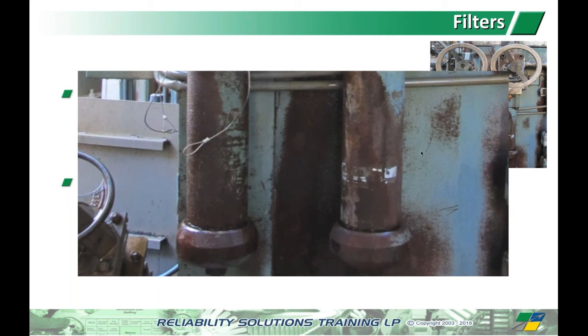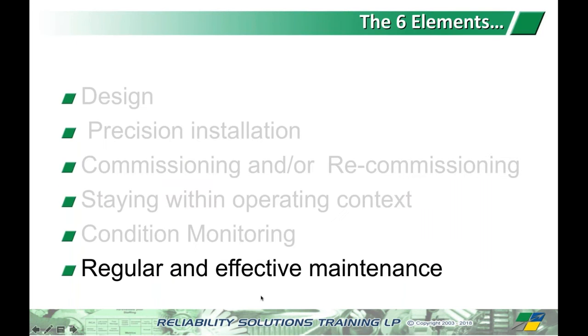They never upgraded the filters. So in terms of filtration, these things were pretty much useless because whenever you were putting fluid through them, they went straight into bypass because we just got too much flow. Okay, and again, we were able to detect that using ultrasound as well. So that's the condition monitoring side of this thing.